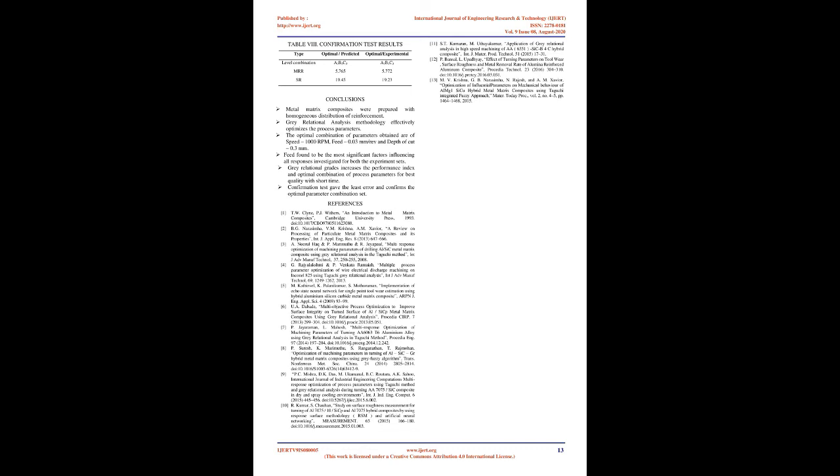The distinguishing coefficient value is generally chosen to be 0.5. Gray relational grade can be calculated by taking the average of the weighted gray relational coefficients and is defined as follows, where w is the weighting factor of each response. In the present study, all process parameters influence the responses, so equal weights are assigned to parameters.